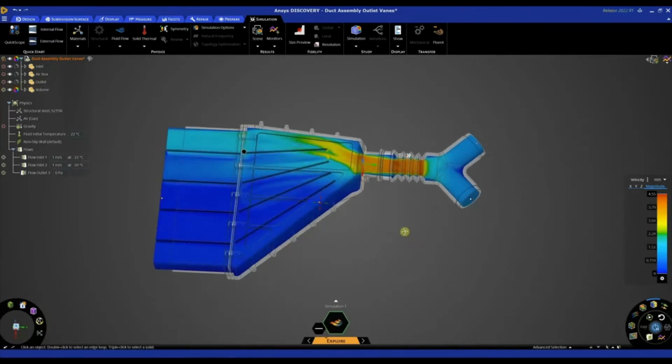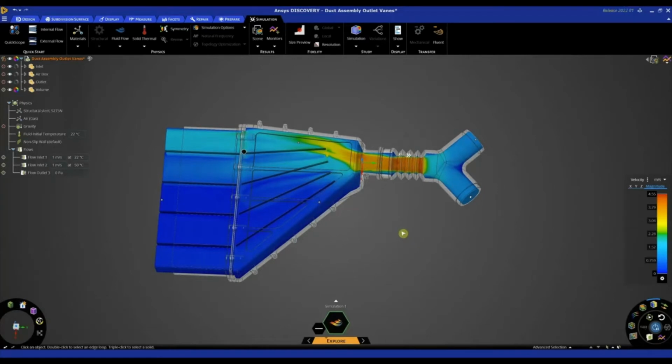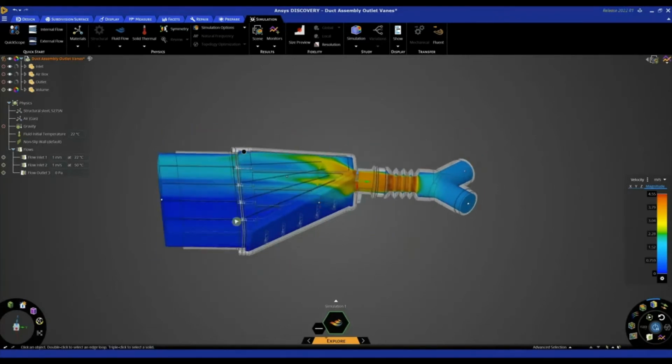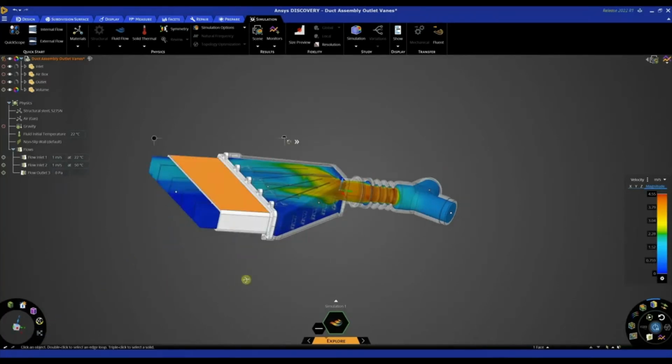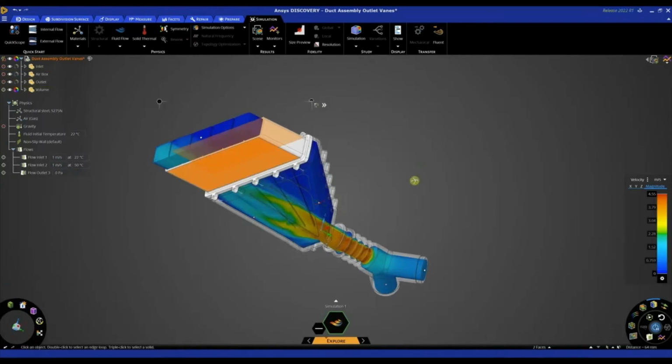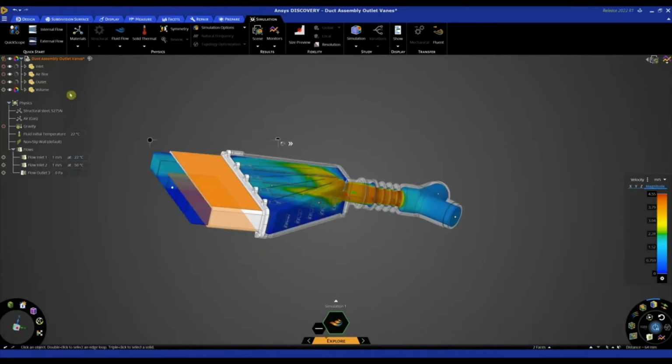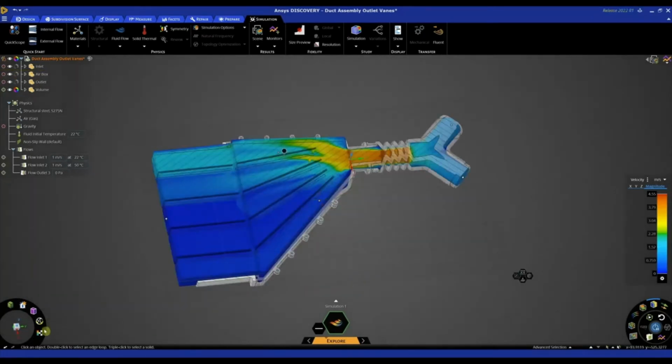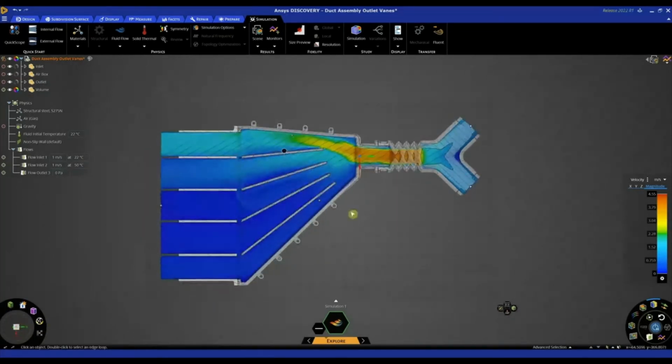That might be something you wish to change. So if you do wish to change that, maybe you can make some design changes. So let's make that non-transparent again. What I'm going to do is section this model through this part. So I'm going to select these 2 opposite faces, go into what we call a section mode in SpaceClaim, and look at it from this top view.